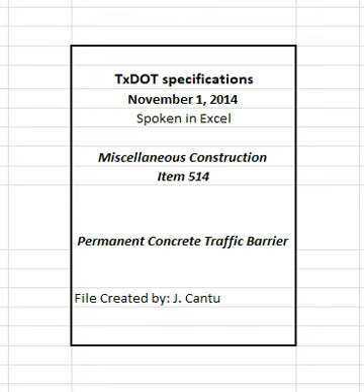3.3 Precast sections. Notify the engineer of the location of the casting site and date on which work will begin if precast sections are used. Form cure concrete until the concrete has reached sufficient strength to permit handling without visible cracks or other damage to the sections. Produce precast barrier sections to the tolerances of Table 1 unless otherwise shown on the plans. Table 1. Precast barrier tolerances. See table in specifications. Repair or replace concrete traffic barrier damaged during fabrication, curing, handling or placing, as directed.